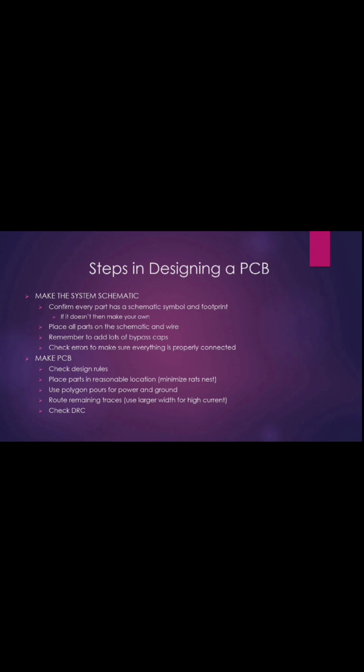Another important phase of designing is to use the CAD software effectively. While designing, confirm every part has a schematic symbol and footprint. If it doesn't have one, just create your own. Perfectly place every component in the appropriate place on the schematic sketch and diagnose it every time to reduce the errors in the final stage.